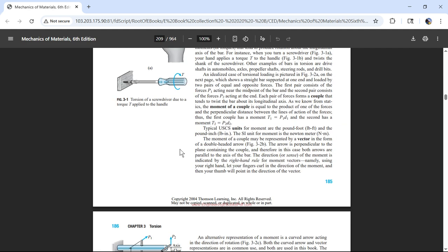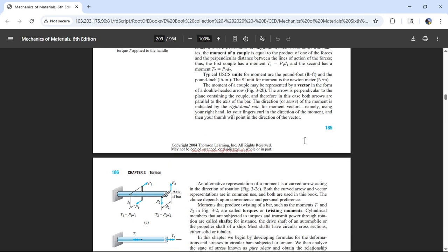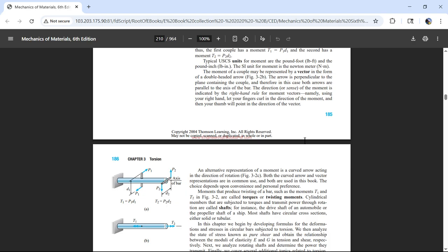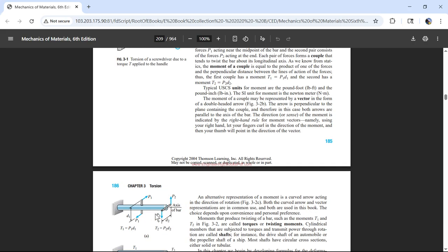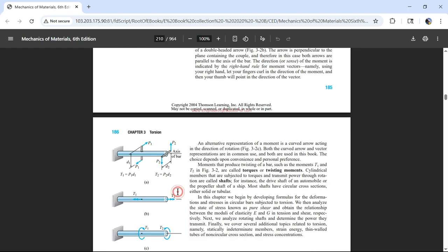All right, cool. So a moment may be represented as a vector. And this is good because some things cannot be represented as a vector, especially in material mechanics. Stresses cannot be. If you cut this face open and you say that I have pressure or stress because I have a force on the face, like let's say it's just axial, in tension or compression, and I make an arrow out of that, that is a tensor. They do not add like vectors, where this will add like a vector.